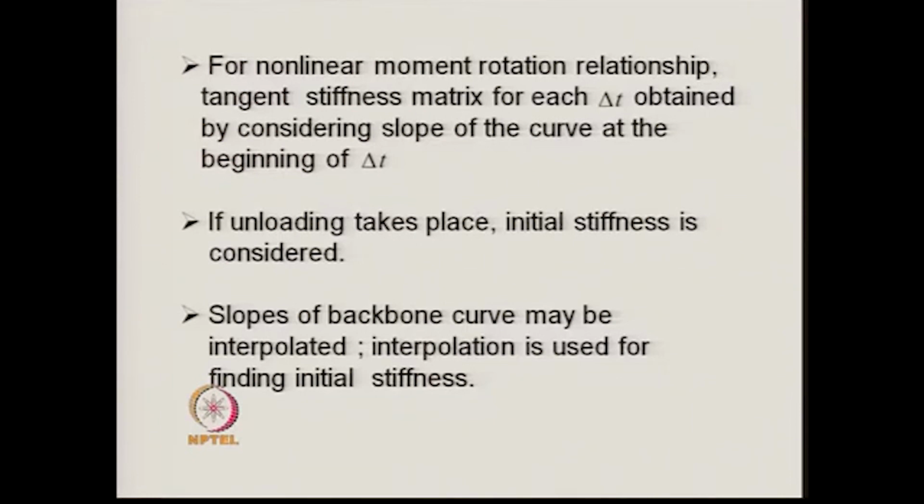Now, if the moment rotation relationship or the force displacement relationship is not idealized as a perfectly elastoplastic or bilinear curve, but by a nonlinear curve, then the tangent stiffness matrix for each delta t is obtained, at the beginning of the time interval delta t.